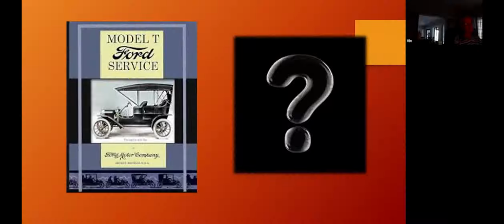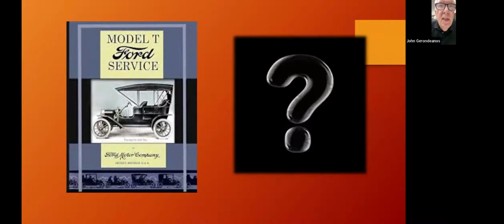I can also explain how professional magnetizers work. They actually work on a slightly different basis. I was involved in making a magnetizer and magnetizing speaker magnets. Speaker magnets are made from ferrite, and they come unmagnetized, and then they're assembled onto their pole pieces. The way these are magnetized is, again, you just have a coil. You don't have any metal parts. But they do complete the circuit with a soft iron keeper.